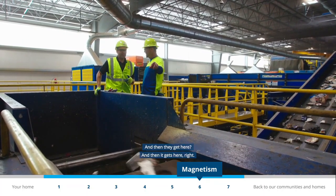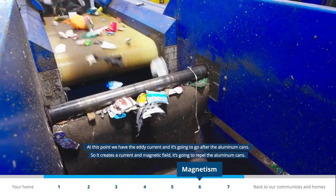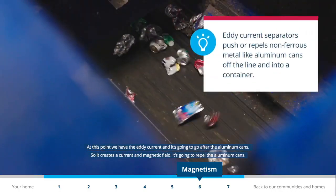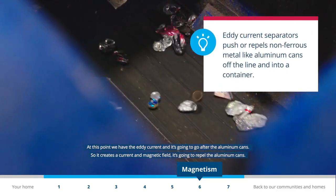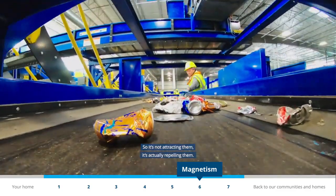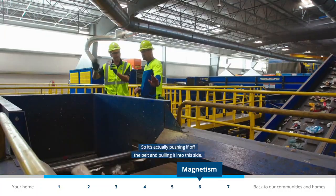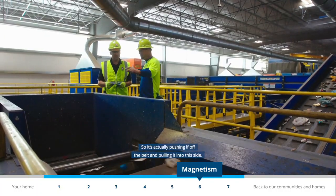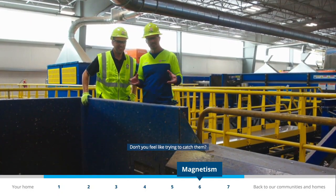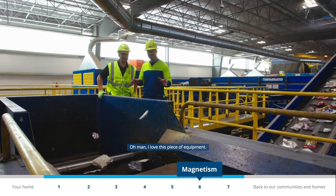Okay, and then they get here. And then it gets here, right? So at this point, we got the eddy current, and it's going to go after the aluminum cans. So it creates a current and it creates a magnetic field. It's going to repel the aluminum can. Okay, so it's not attracting them, it's actually repelling them. So it's actually pushing it off of the belt over into this side. Correct. Don't you feel like trying to catch them? Oh man, I love this piece of equipment.